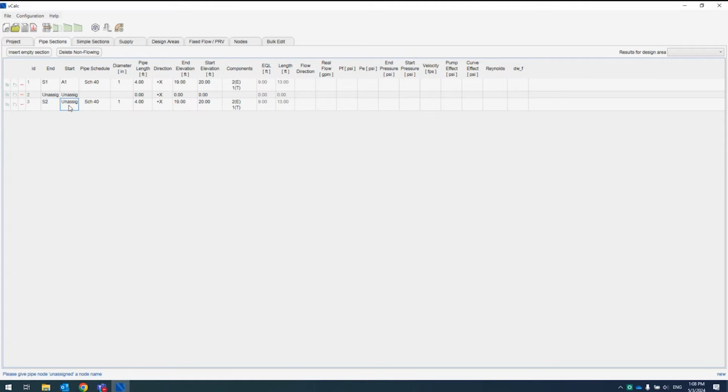So if I had a bunch of typical sections here, all I would have to do is come in, click that duplicate button, and continue filling in the typical information here. The third option is the leftmost, which says copy row. And if you were to click that, you can see that it carries over quite a bit of the same information, but it's starting to try to automatically node up some of the pathing for us. So it's going to take the start node of the row you click that on, put it as our end, and then it's just going to pick our next available default node there. So a couple different options to try to reduce a little bit of duplication of input there.